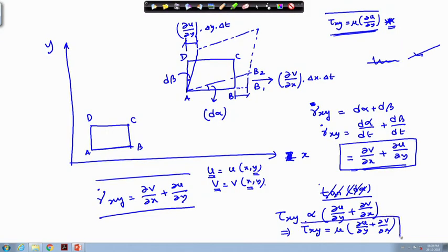And then from there you correlate that your shear stress is proportional to the angular deformation, which for a small deformation is the summation of the two velocity gradients, and where the shear stress is linearly proportional to the summation of the two velocity gradients, then you have a Newtonian fluid. The advantage is that the moment one talks about a 1D flow, depending on the flow field, one of the terms gets cancelled and one can very easily get to this expression.